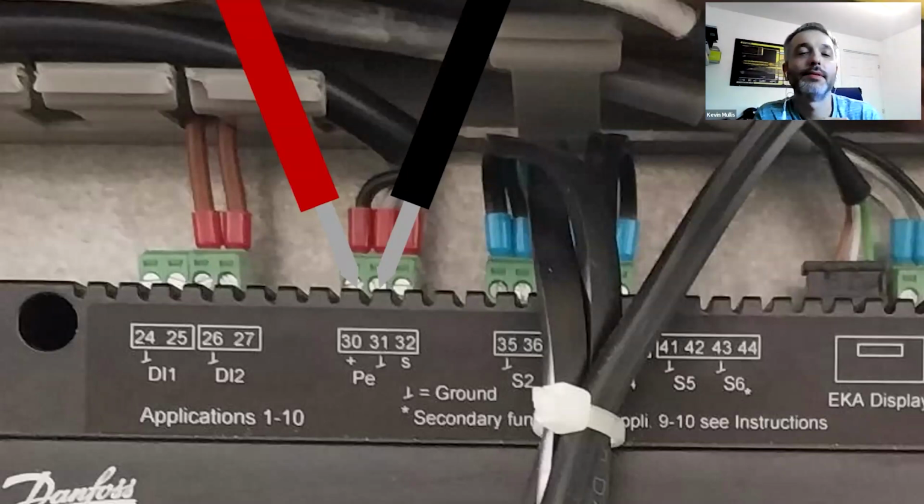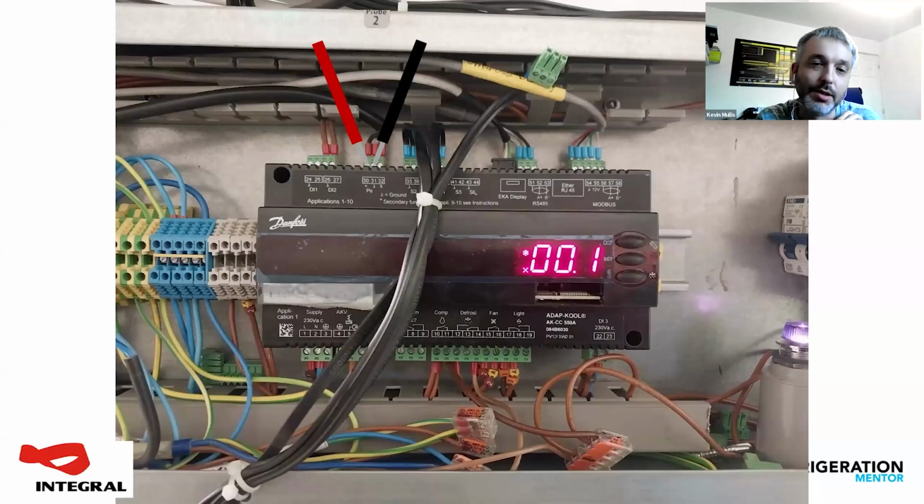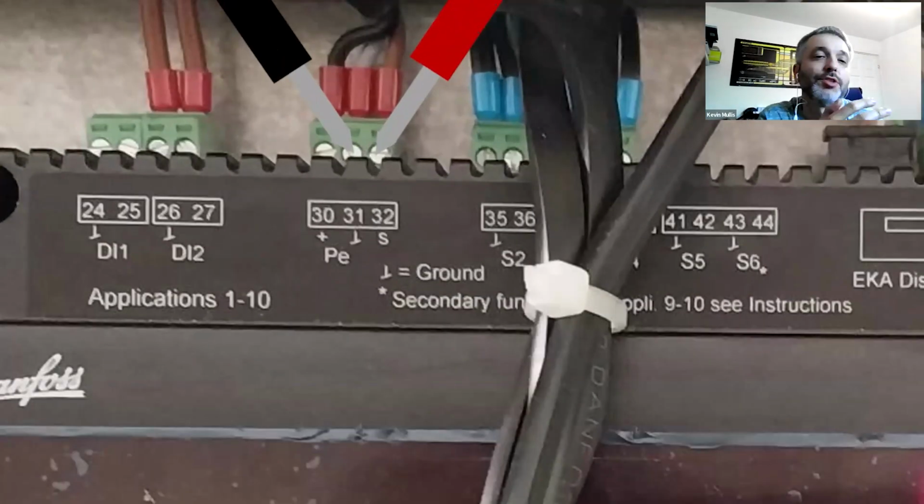Yeah, of course. So in this application right here, this is one controller with one transducer. They're all ratiometric 5-volt transducers, so they need a supply, a ground, and they give you a voltage back. So 30 and 31 there is your supply and your ground, which you've got the probes on. You should see 5 volts DC between those two. If you go between ground and S with your probes, you will see the proportional signal back. That's your pressure reading effectively.